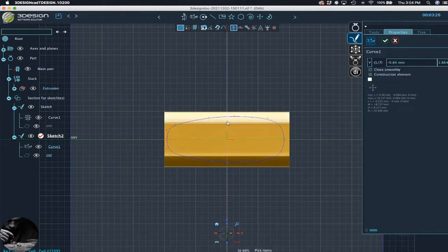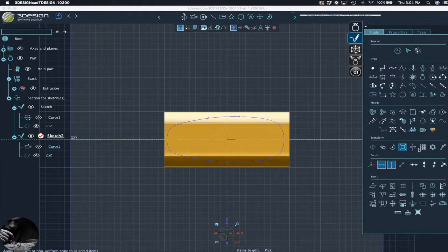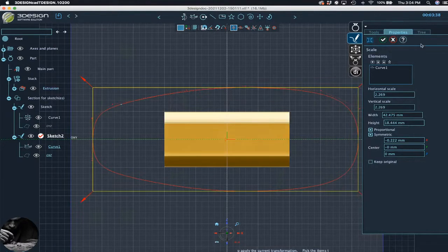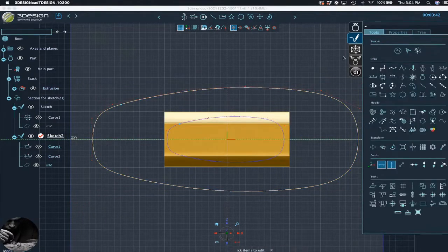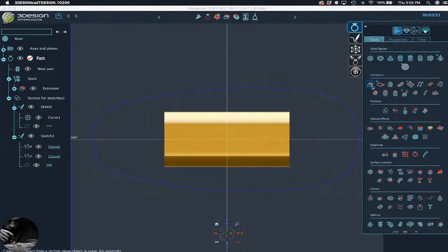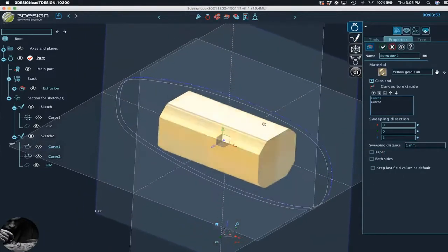The other factor is that we need another line on the outside of this because of what we're ballooning. So all I have to do is make this one bigger, and it just has to exceed the perimeter of the piece there. All right, we're going to keep the original, select it, go back into the tools, get back out of sketch there, and use my first extrusion here.